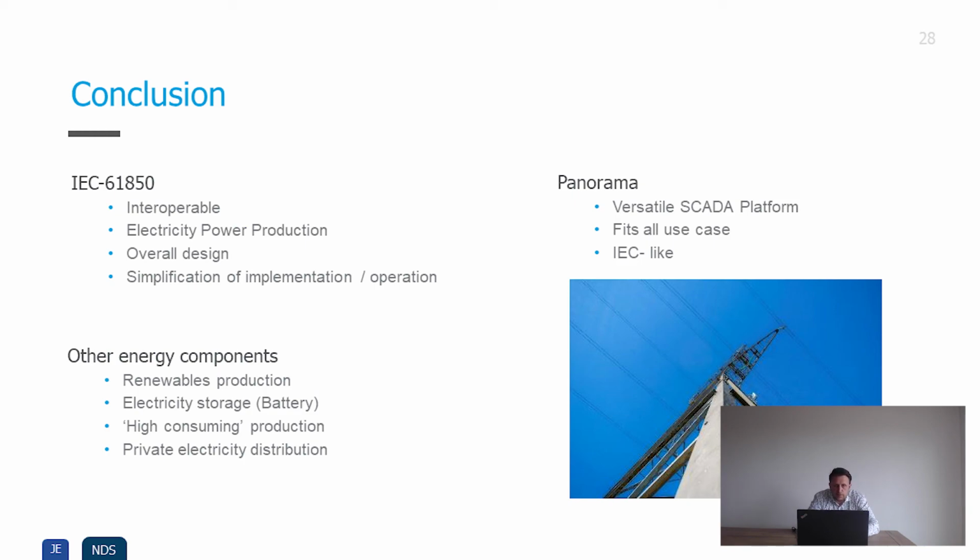Well, first of all, the interoperability. The IEDs can now communicate with each other without any problems. And the standard was designed for the power industry. With that in mind, it has some very useful features such as GOOSE messages, which lower the cost of hardwiring, but also sampled measured values where you can get values directly from the sensors.